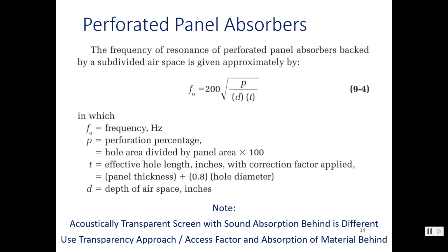But a lot of times it'll also have a metal layer with a bunch of perforations in it to protect the material. Silencers that might go in your HVAC system would have those perforations in it. Acoustical louvers for your HVAC systems. There are lots of places where you might have these things that are meant to protect and hold in place the sound absorption while still exposing it to the sound as much as possible.